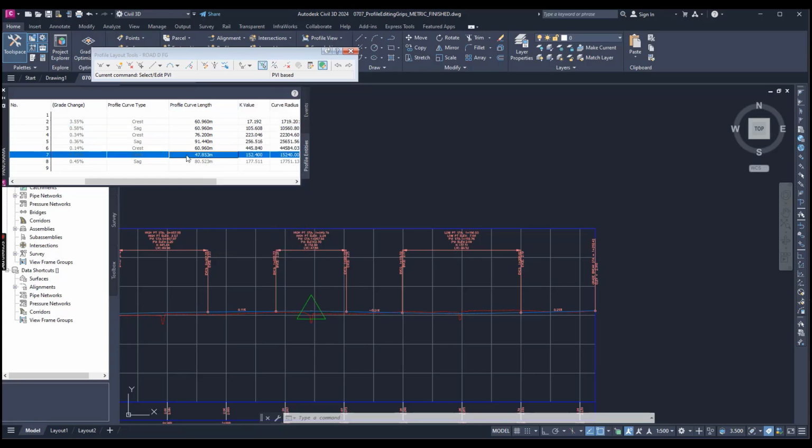If you want to resize the column, drag the breaks between the columns, or double click the break between two columns to auto size to the column content. Just double click the profile curve length value for entity 5 here, and you need to change it from 91.44 to 76.2 and just press enter.